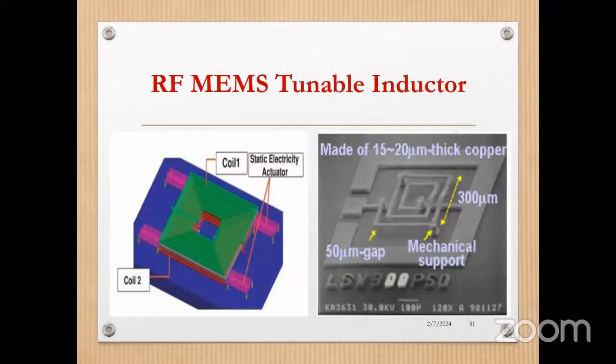It should be something like a square, so that what is placed above the PCB gives me a reduction in thickness of that electronic component after packaging. So the right side diagram shows the planar inductor. This is also a tunable inductor where I put a MEMS switch over this so that I can vary the inductance value also. So this is another important device that is used in RF applications.